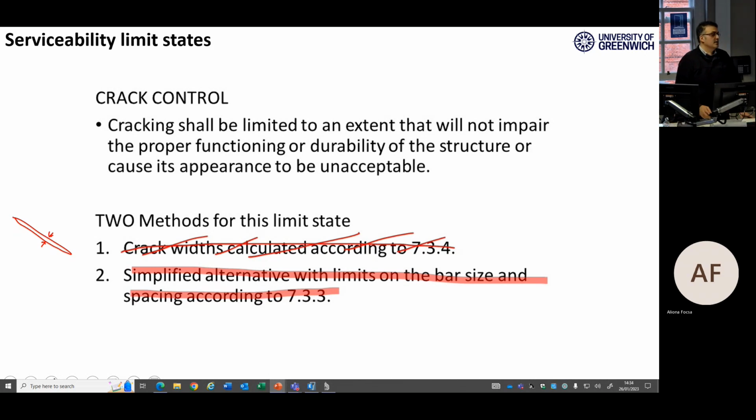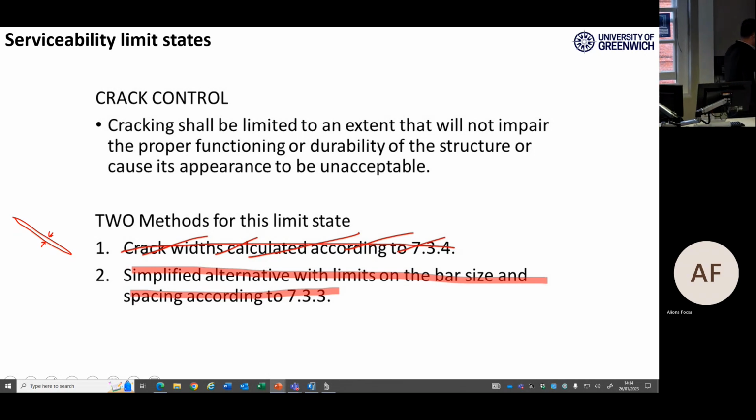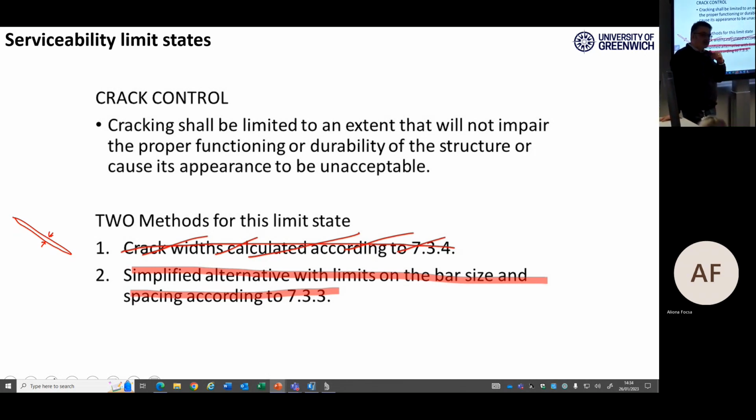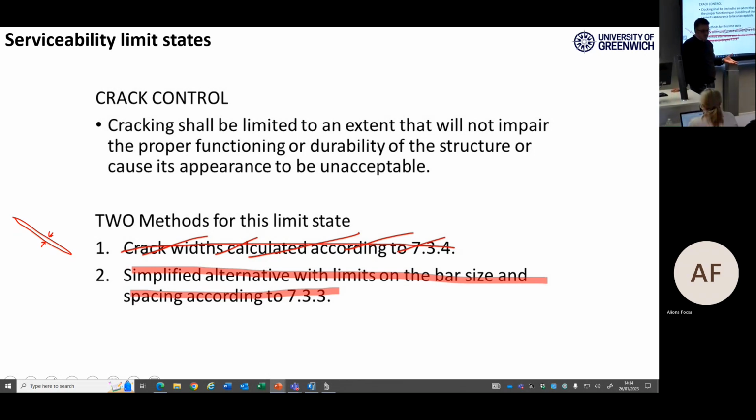In addition, the crack problem is that principally air can go in, water can go in, right? If water goes in, your rebars will have some corrosion over time. So it won't work as it's supposed to.